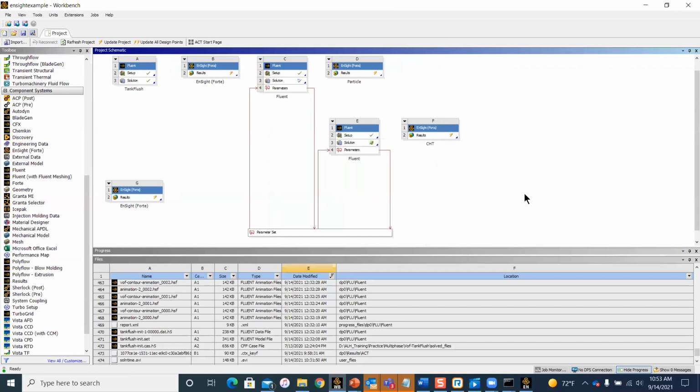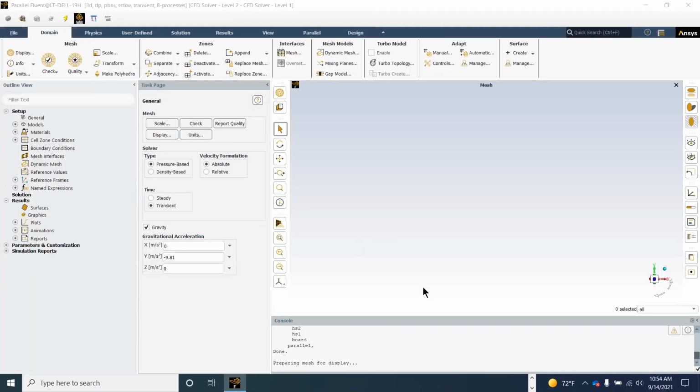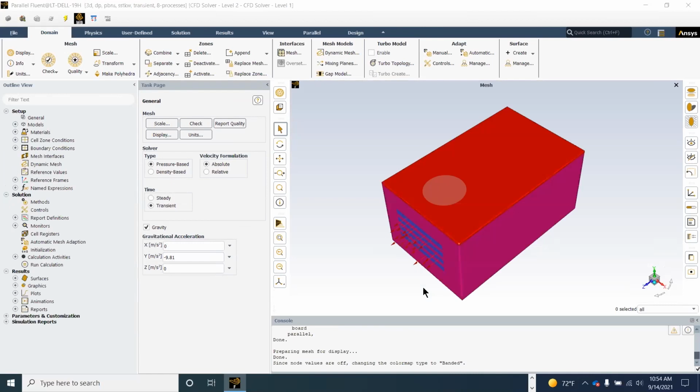Fluent side of things. So for example, I am doing a transient simulation in which we have some discrete phase particles, right? So how do I go about exporting the particle data, which is separate from continuous fluid data, and import it into EnSight? So let me go ahead and turn on Fluent. So this was the same case that I was just showing you guys. But the difference between that case and this case is this was solved in a transient way.